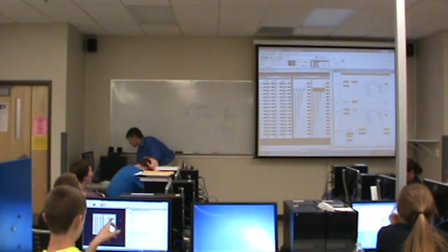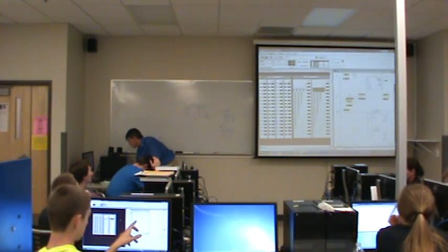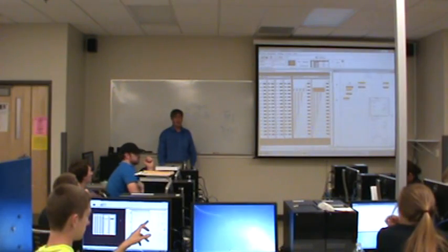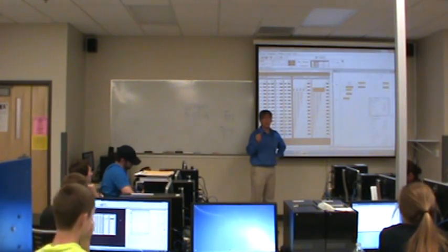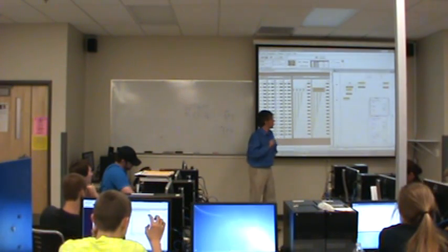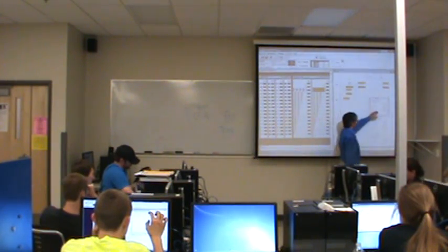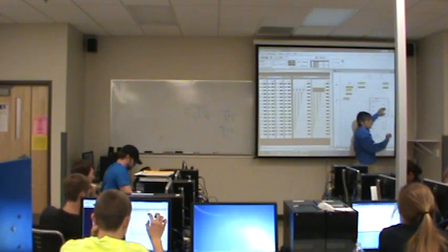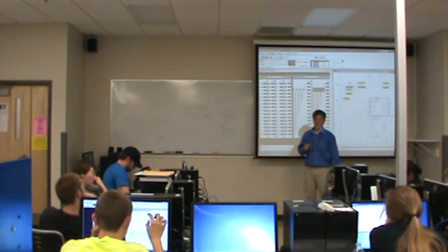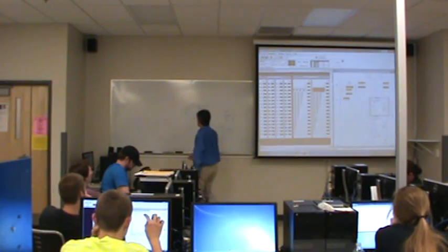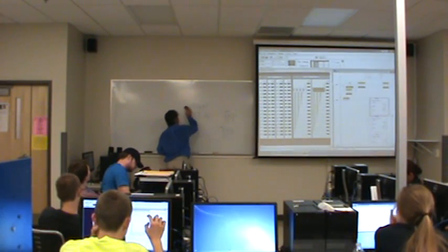And a mask is a general concept that's really important to understand because these are masked moves. I may want to write data into memory and not overwrite certain bits. There may be only certain bits that I want to write. So you can put a mask in here so that only certain bits would be forced on. The others would be unchanged. Okay? So, for example, let's say I want to use a move instruction to copy data.